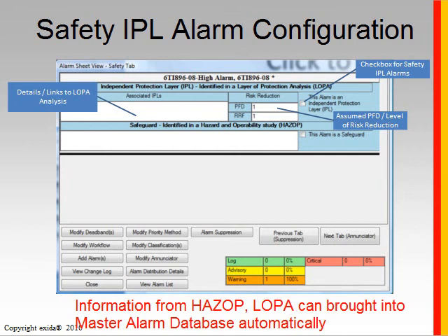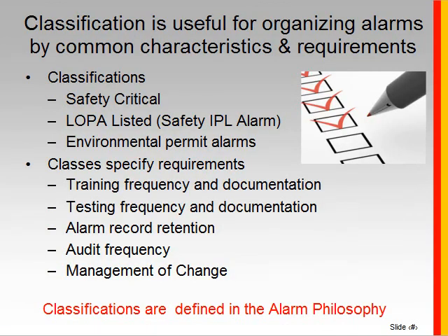And this idea of keeping track of alarms, the type of alarm, and special attention is what's called classification, which is another key element of the alarm management life cycle. Here we want to classify each alarm as a way of helping us organize and manage them all. Classification is not an attribute for the operators to use. It's really for the designers and managers of the system.